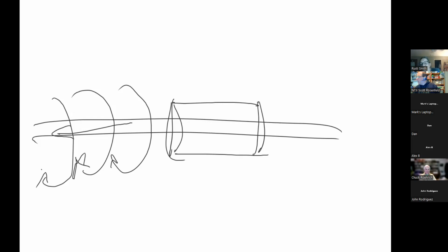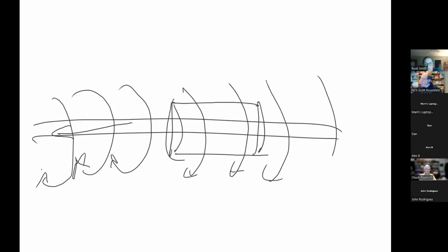It's a tuned device that's made of usually powdered iron and cobalt that's baked into a shape. If there is a magnetic field at a particular frequency flying around the cable because of the current flowing through the cable, that magnetic field gets concentrated in that material and gets burned up as heat. Oh. Nice. Good to know. Yep.